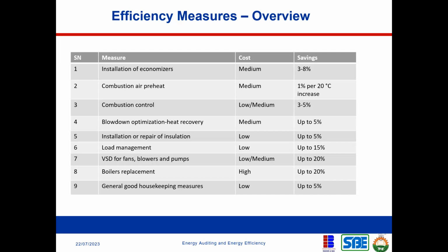So the air that is going into that combustion, you can preheat using the recovered heat. You can recover the heat and then inject that air back into your combustion chamber, just like introducing that heat back into the combustion system. And by doing so, you reduce the amount of fuel that you need to achieve complete combustion. I will explain that with a diagram. It might look ambiguous, it might look vague here.